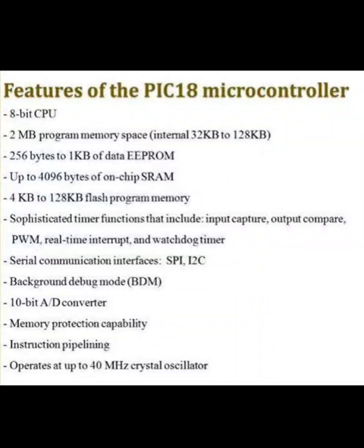The data memory of the PIC microcontroller is 8-bit wide and the program memory is 12-bit or 16-bit wide. PIC devices also include a built-in analog to digital function, power-on reset and brown-out reset features. Brown-out reset means that when the power supply drops below a certain voltage, it causes the PIC to reset. The oscillator frequency determining component of the PIC can be a low cost RC circuit, a quartz crystal or a ceramic resonator.